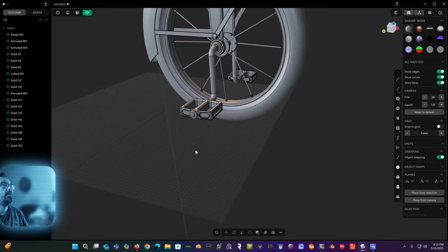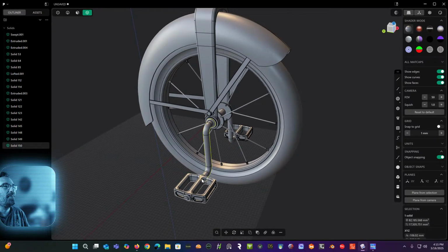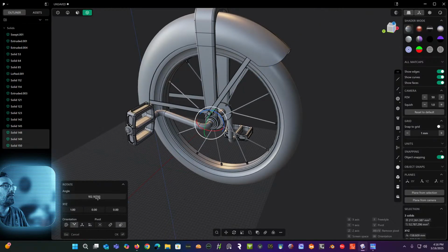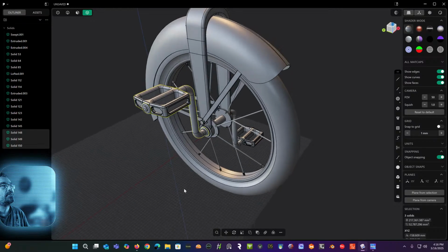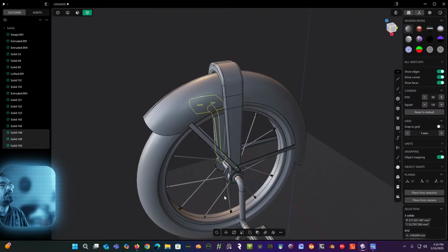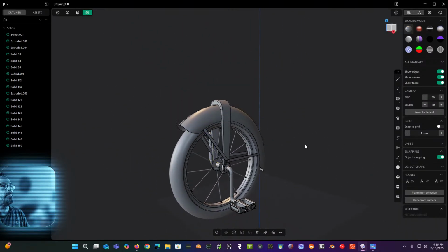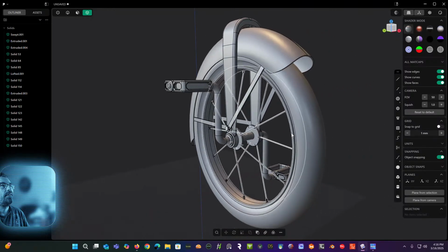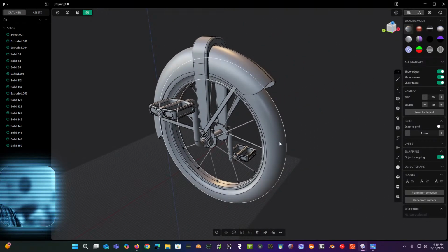Now, if you notice, you can't ride a bike like that. So I'm going to take this piece and rotate that 180. So we're going to go here. We're going to take our V where this center should be. It should be there. I'm going to go up here and put in 180. It should wind up perfect. As far as I can tell, it is. So it's a lot like a unicycle I made once here in Plasticity. But yeah, looks great. I think for the moment, this is great. This is essentially half of the unit.